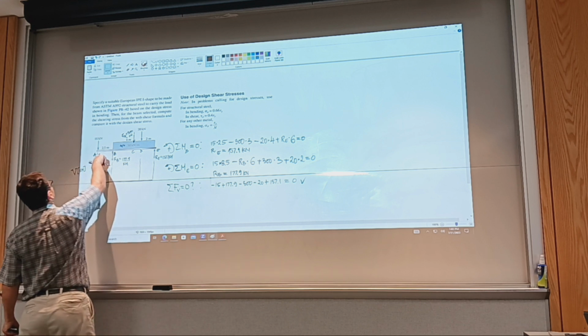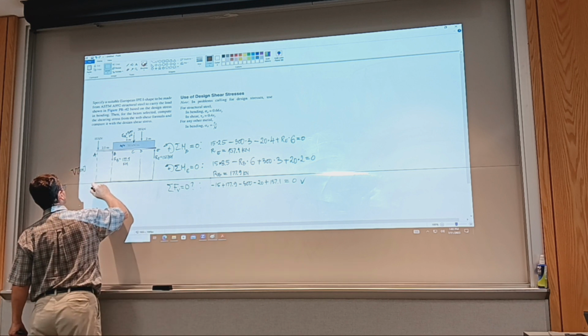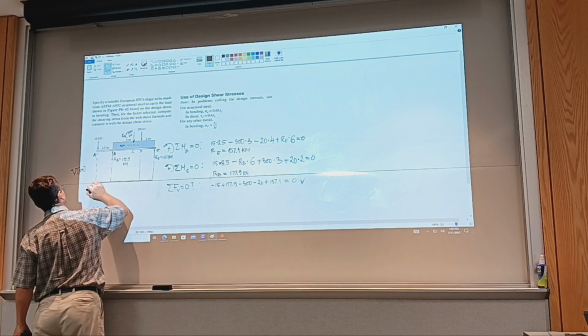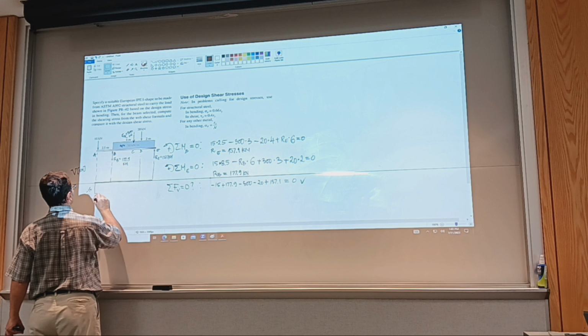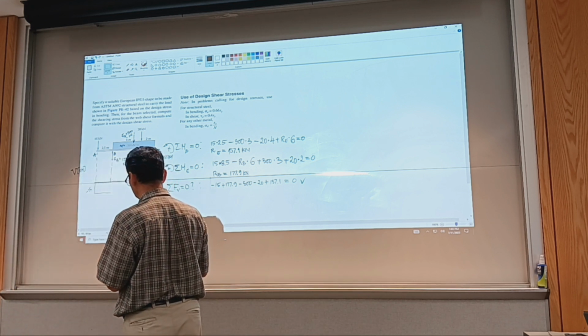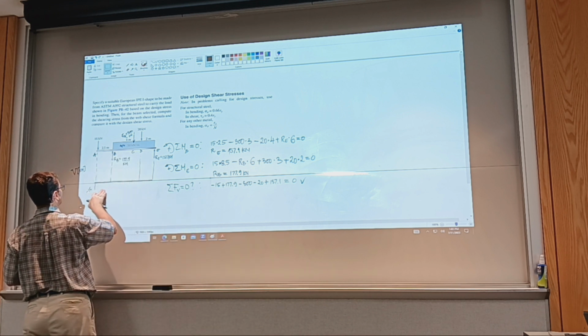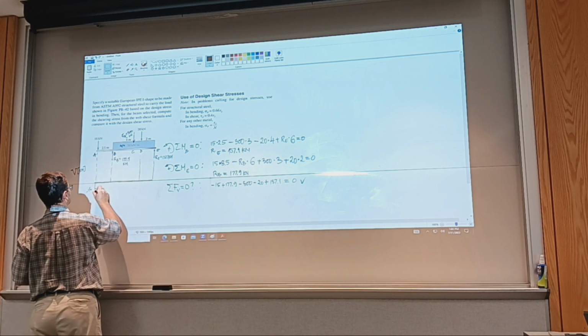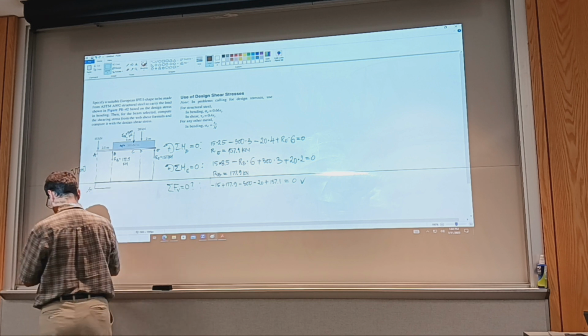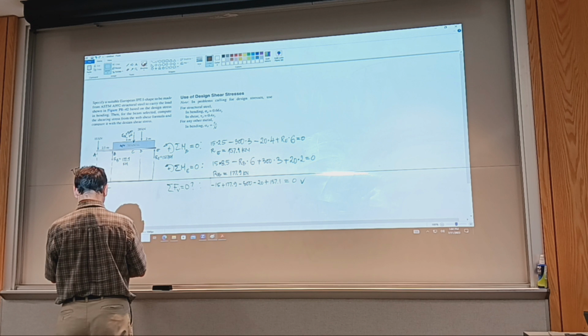Okay, so 15 kilonewtons is down, so there's a negative, so the diagram starts with negative 15, and then I go horizontal, nothing changes, and from 15, which is a little bit big on the diagram given the values that I'm encountering later, I add 177.9.